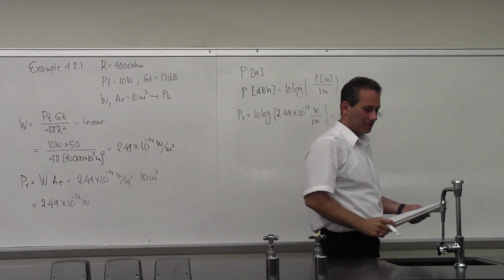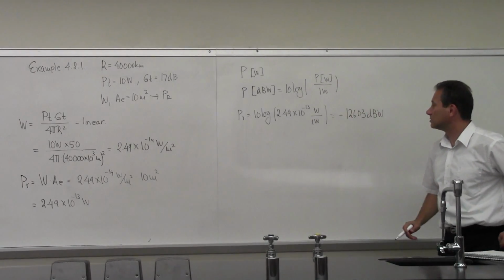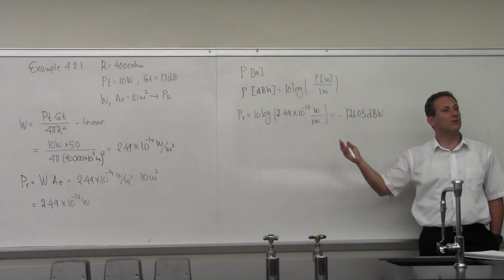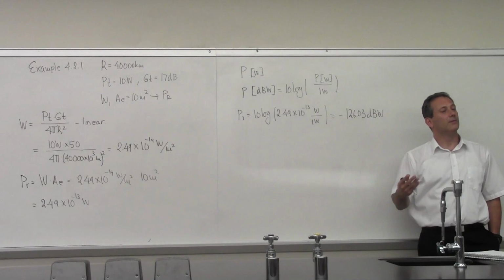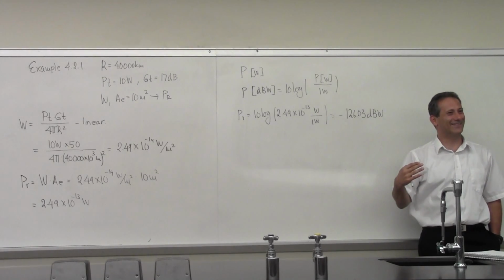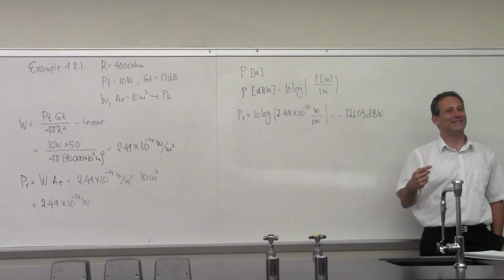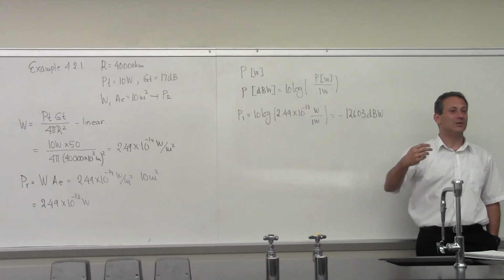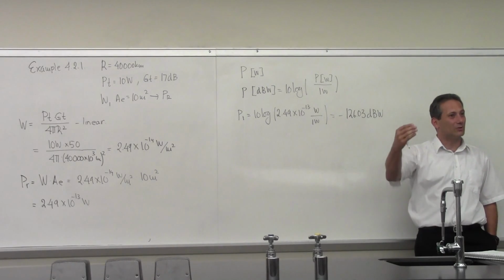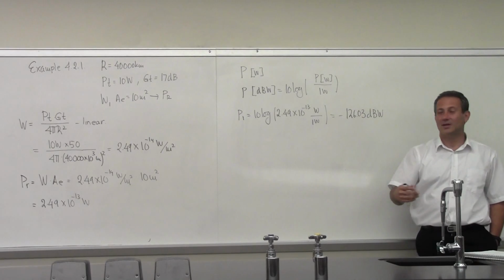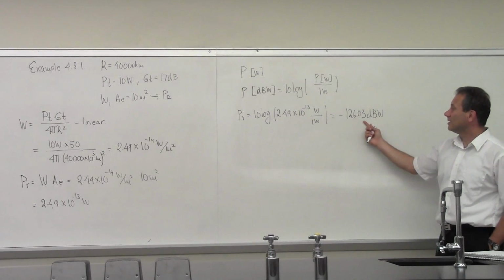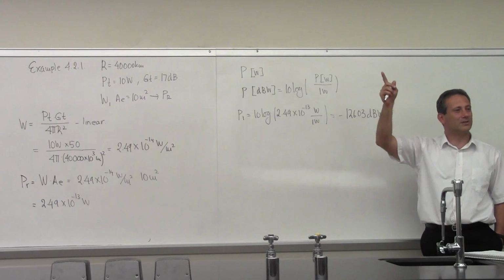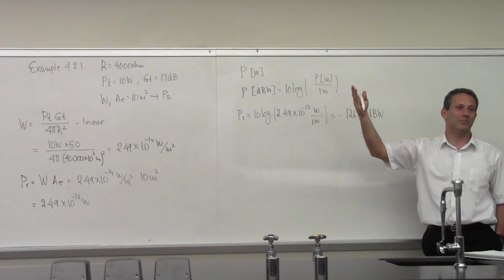For my RF propagation students and PCS students, we know that the offset between dBW and dBm is 30, but which way? That's always the question. Milliwatt is a smaller unit, so the number, when you express it in milliwatts, is always going to be a larger number, right? Because you're comparing it against a smaller unit. So if you want to express it in milliwatts, it needs to be 30 dB up.